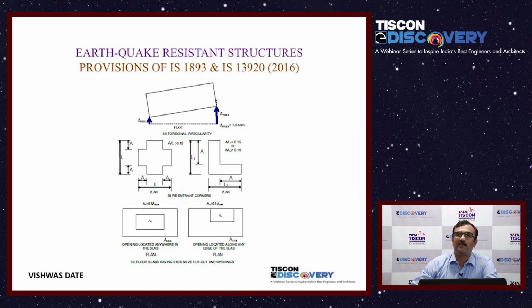These are some of the examples of atrium areas. Now why do atrium areas become critical? Because if you can see, the slab distribution will prevent the force traveling effectively from one side to the other because this slab is too thin. Or in this case, this structure actually gets isolated practically because of a large atrium opening around the edge. Now does it mean that we can avoid all of this? Perhaps no. Architects might still want this as a part of a feature in the building. It just tells us that we need to be more careful about those structures.